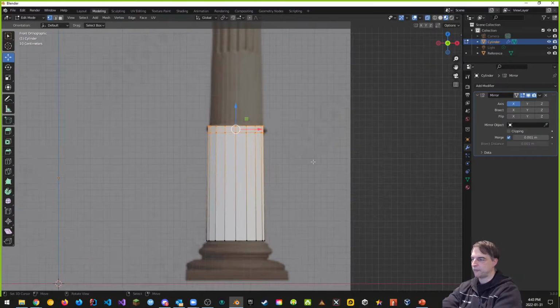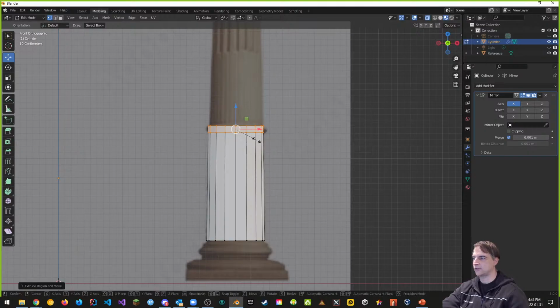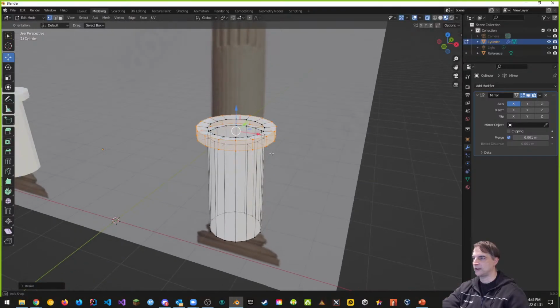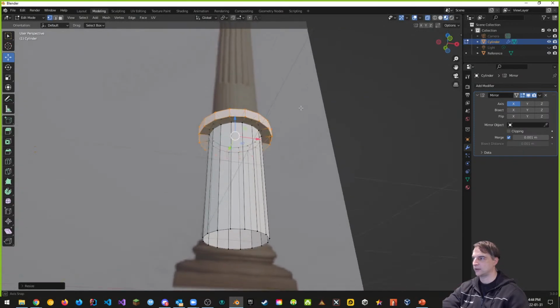Again, I'm going to look at it from the front for a second to get a better, more controlled view, and I'm going to extrude. So press E and then press Enter. And then I want to scale across, for now, just the x-axis, so this way. So extrude, scale across. If I do it this way, it scales in both dimensions. So if I showed you what that looked like, it looks like this, which isn't terrible, actually.